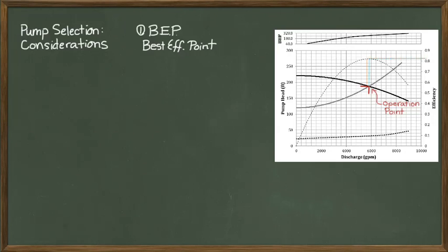But when we talk about efficiency, you may think, well, what are we talking about in terms of efficiency? Well, for pumps, if we put a gauge on the downstream side of our pump, we could measure discharge and head coming out, right? And if we use this formula here, we can calculate what is known as the water horsepower. In other words, the amount of power that is observed in the discharge and the amount of pressure head that's coming out of our pump.